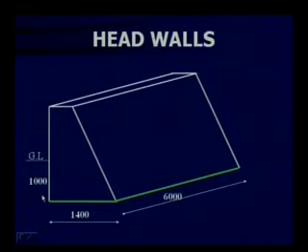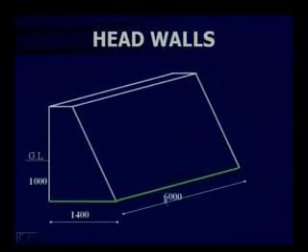In any calculations while preparing a detailed estimate, you need the length, width, and depth. Generally, we dig slightly longer. This is 6000 mm, that is 6 meters. So we'll give a tolerance on either side. Just have 20 mm on this side, 20 mm on this side, so that the marking can be done accurately inside the pit. Now shall we see the calculations?